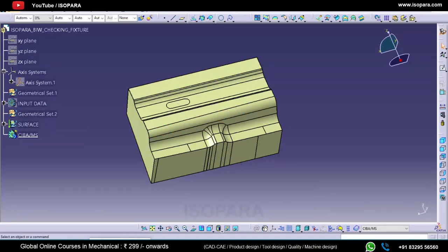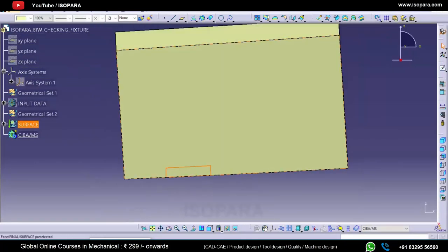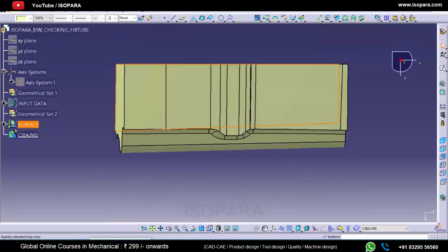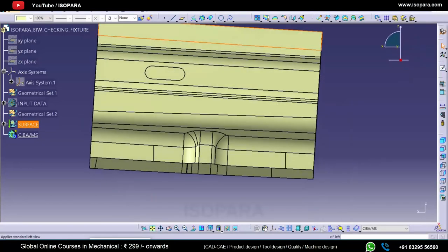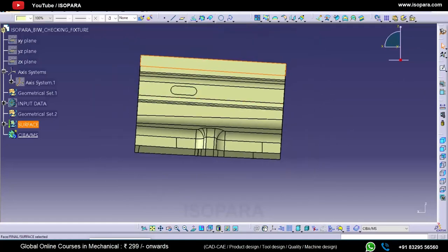So if we take any material, there will be two settings only. So if you want to save the machining setting for this undercut, then we have to split this block and do the individual machining for these separate blocks, because that face is in the undercut.